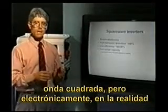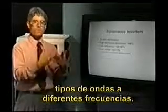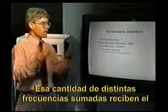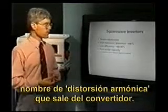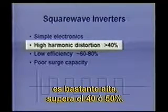But electronically, a square wave is actually made up of an awful lot of different types of waves at different frequencies. We call the amount of different frequencies added together the harmonic distortion that's output from the inverter. The typical harmonic distortion output from a square wave inverter is quite high. It's greater than 40%, 50% or more.